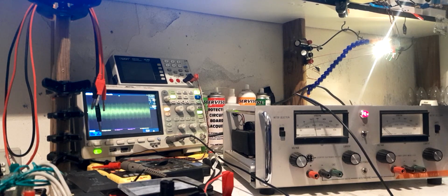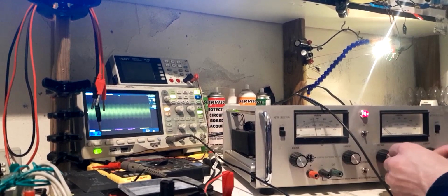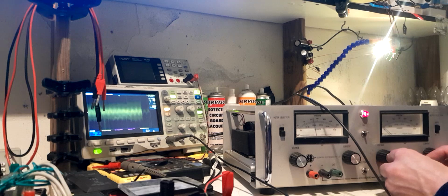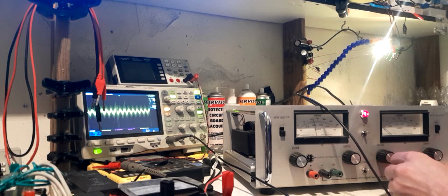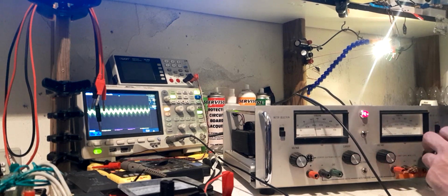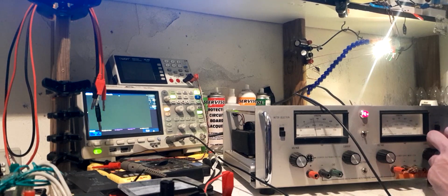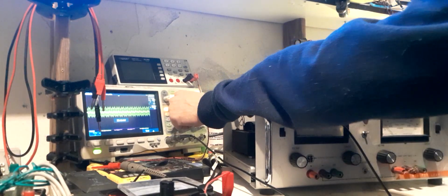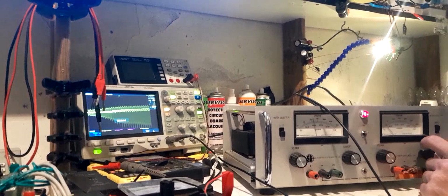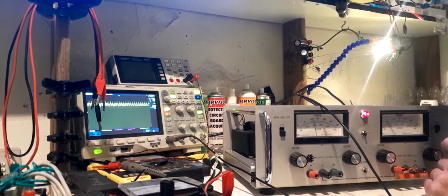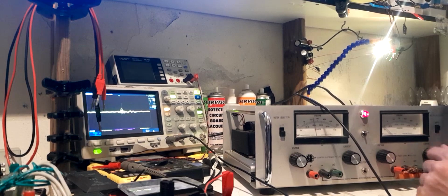I don't think you can see the Zener noise through that, because Zener noise isn't that large. I mean, it can be, but I don't think it would be at 5 milliamps on a 3.6 volt Zener. But I could be wrong. But the fact that when I load it, it changes like that, and the oscillation breaks out into different forms, just as it was with the TL431 in there, I think we can confidently put the references back in.